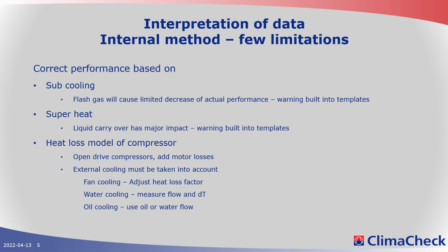So check your subcool and superheat. Does it make sense? Is it what you expect? Before you start collecting real data.